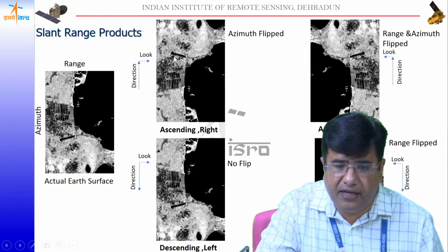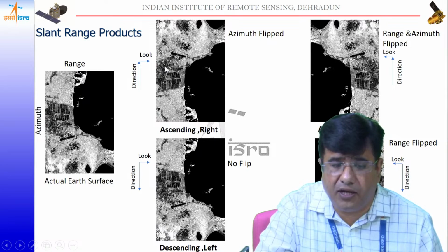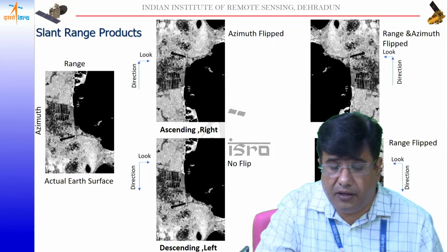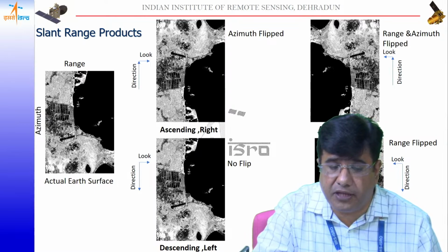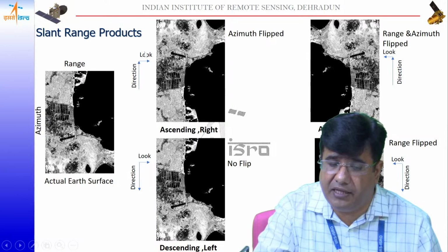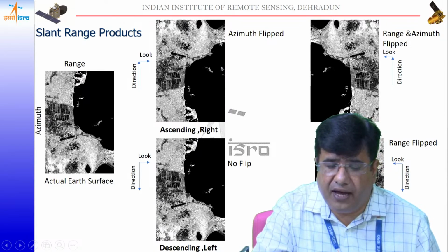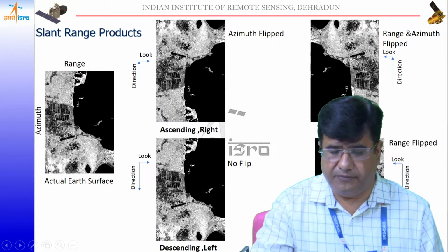Geotagged means that in this image we have the information of latitude and longitude, but it is not projected onto the ground. Only the information is available, but it is not actually projected on any datum or geographical coordinate system. So it is a normal image, a normal L1 data, with some lat-long information for the pixels, either grid by grid, or as the four corner positions.